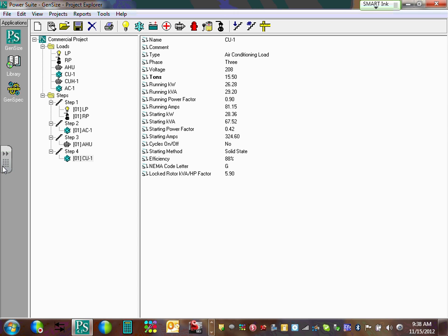How do you achieve this? 2 ways. Auto transfer switches, which we only have 1, or you interface the controller of the condensing unit with the controller of the auto transfer switch. So when it starts, it sends the signal, start a timer basically. It starts timing, wait, bam. Can I have thumbs up, Chad?